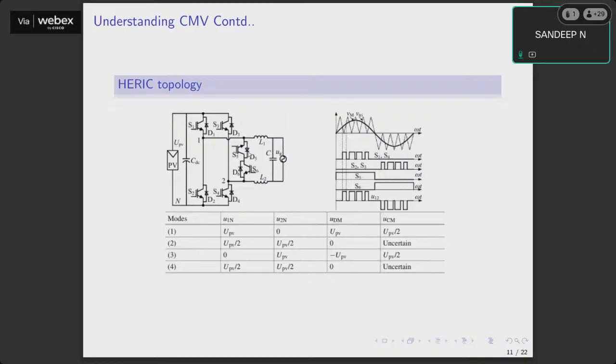They are trying to disconnect the path for the leakage current. Now, from where exactly is the path getting created? You have the AC point grounded here, and you have a capacitor that originates from here and gets connected here. So the overall idea is, if we can break this path during the process of switching, then we can reduce the leakage current, because ultimately you are disconnecting the common mode path for some time in a switching period or in a cyclic period.